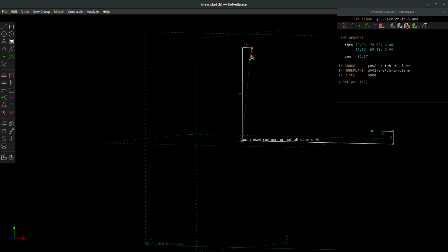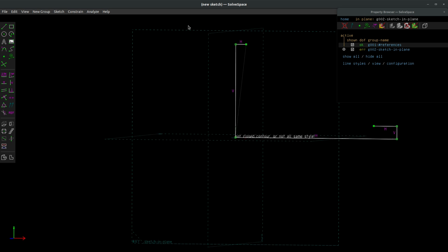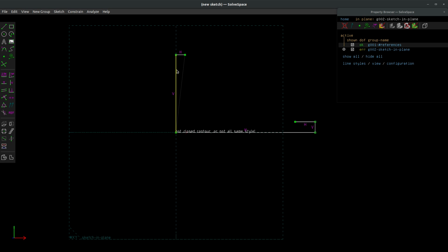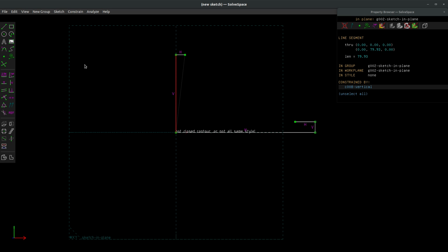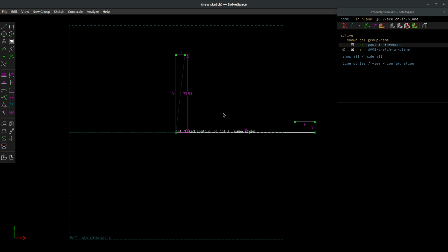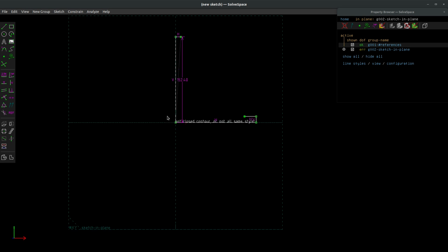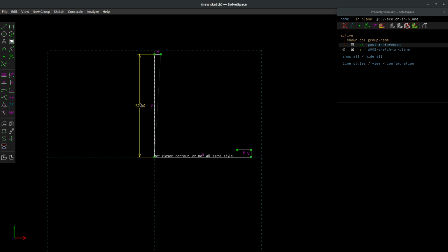There's the horizontal constraint. W will make your view normal to the work plane again. So I highlight this line and choose dimension. And we'll add in 152.4. There's a full set of hotkeys for vertical and horizontal like I use in FreeCAD.